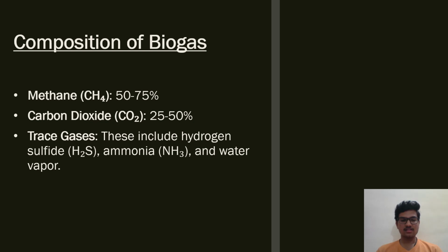The digester is an airtight, waterproof container with a means of entry for biomass. Here you introduce the raw materials to be transformed into energy, then agitators shift the biomass periodically to free the gases and prevent the formation of layers. The gas holder is an airproof container, preferably made of steel, that collects the gas generated during the fermentation.